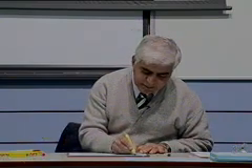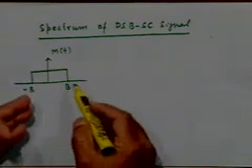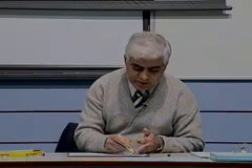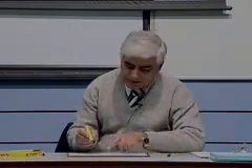So let us say M(f) is a low pass signal. Again, when I draw a spectrum like this, it is not to depict that real signals will have such spectra. They may have any arbitrary shape. Of course, if it is real it will be even symmetric, but otherwise it can have any arbitrary shape. The important parameter here is the bandwidth of the baseband signal, which we are assuming to be B. So what is the nature of X(f)?